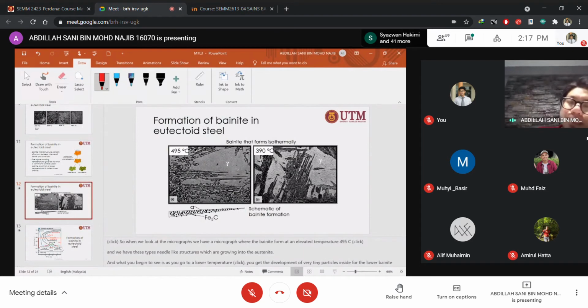So bainite, compared to pearlite: you have the grain, and then it has alternating layers of iron carbide and ferrite. So this is pearlite. And bainite is like a broken lamella. It's non-lamellar, but it's the same, still ferrite and iron carbide. And also it has a needle shape.